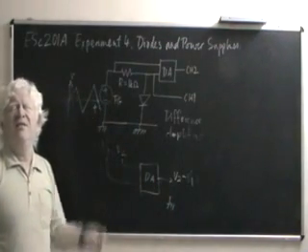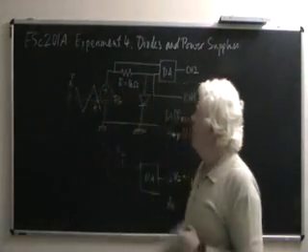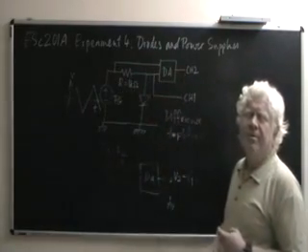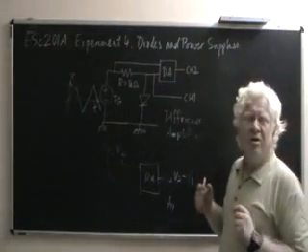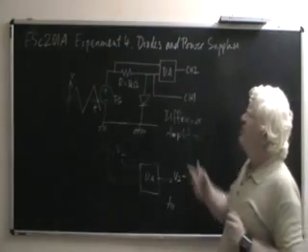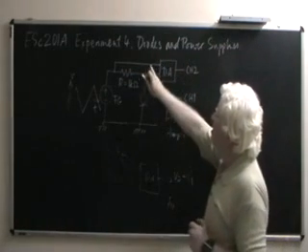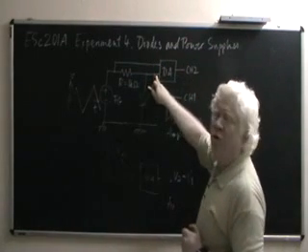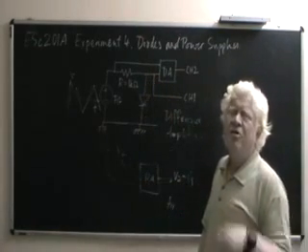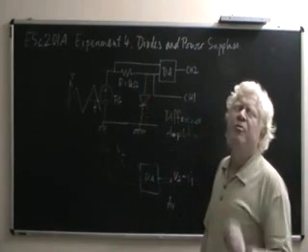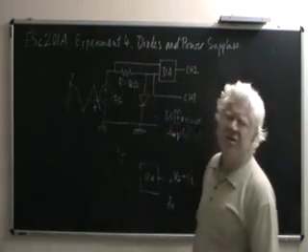This is the task that needs to be done, because for either channel of the oscilloscope, one end of the two terminals of that channel is already grounded. So if we take these two wires and connect them to one channel of the oscilloscope, for example, if I connect this and this, then the oscilloscope will itself ground this point. So there will be no voltage across the diode at all. Hence, an oscilloscope can measure only voltages with respect to ground. It cannot measure a floating voltage, which is what you will find across this resistor.